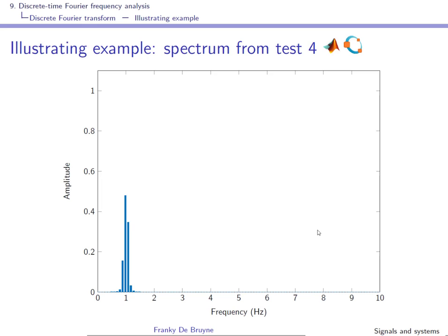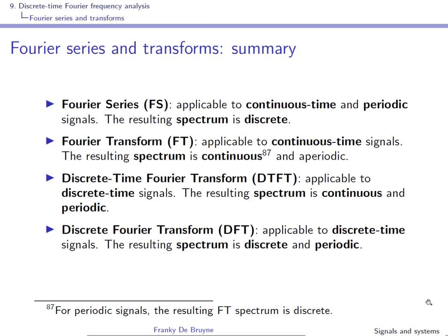If you do that, you won't have any problems with spectral leakage, and there will be no need for windowing. Another conclusion is that zero padding is a very bad idea when you want to compute the amplitude spectrum of a periodic signal.